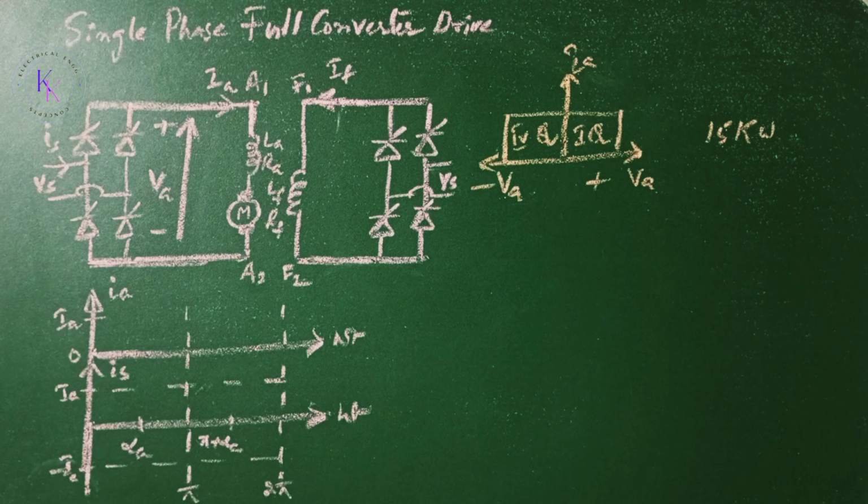During regeneration, for reversing the direction of power flow, the back EMF of the motor can be reversed by reversing the field excitation. The converter in the field circuit could be a semi or full or even dual converter. The reversal of armature or field will allow operation in the second and third quadrants.